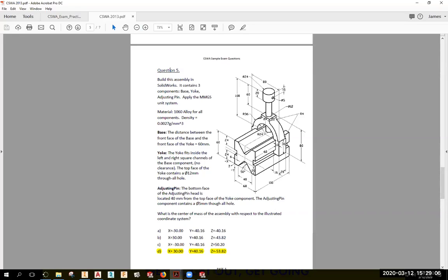No. All right. Yeah. I don't care. Try either one. You've been doing a lot of bottom up, so if you want to try something new, try top down. If you want to keep doing what we've already been doing, then do bottom up. If you do Fusion, you're probably going to do top down because it's easier to do that. That's how Fusion is meant to be used. Doing bottom up in Fusion is actually harder because the updates take longer when you change pieces, but you can do it either way.